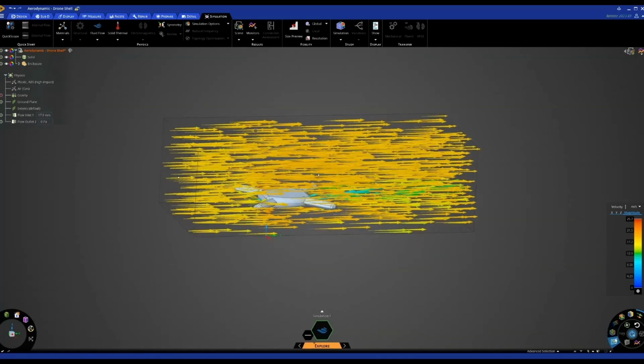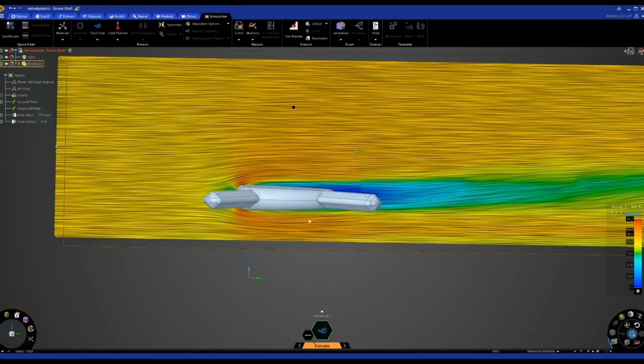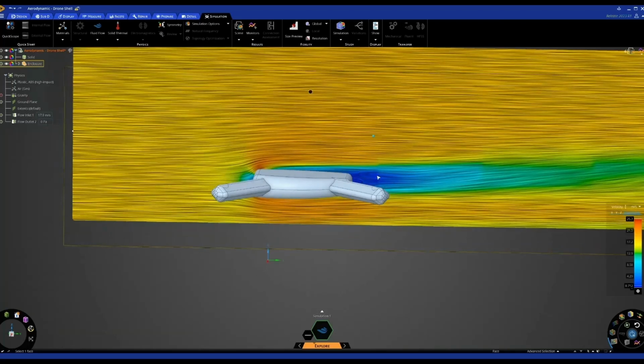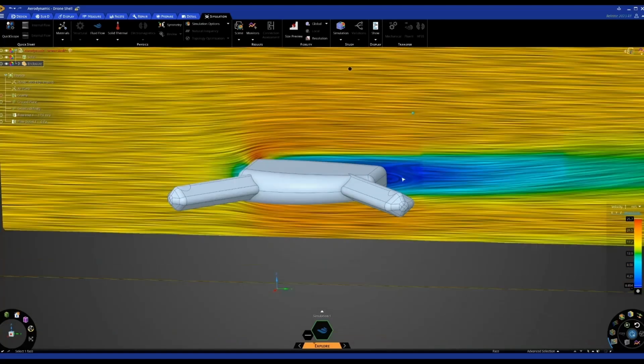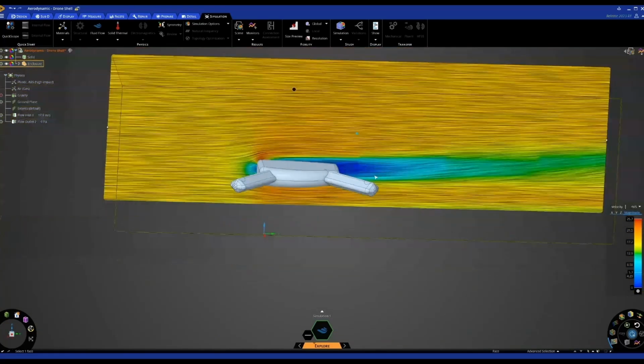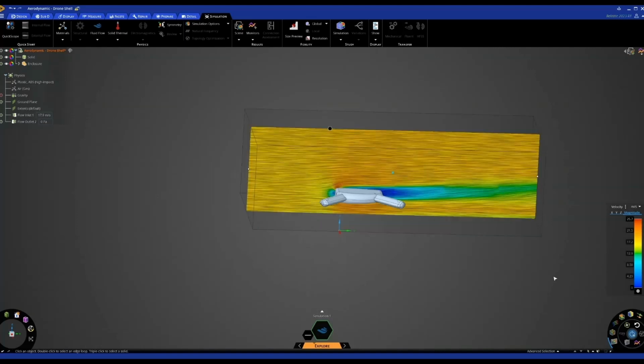So now that's complete, we can start to look at our direction field. And straight away, I can see probably a smaller separation region for sure. Again, maybe less turbulent flow as well around the exit area. So you can straight away see an improvement from going from one design to another. So that's all the evolution as the design goes along. We can simulate as we go and see those improvements, and obviously we can also validate them with the actual results themselves. So that's just a quick example of external fluid flow on our drone.